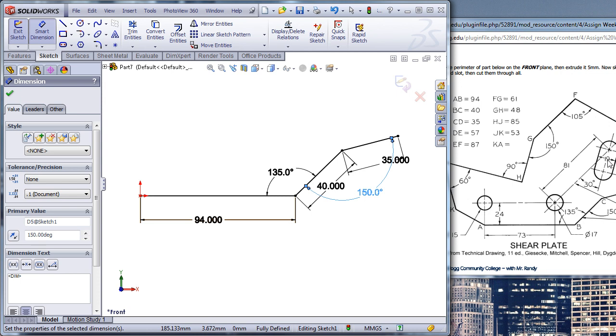You should be able to handle it from there. Again, don't do diameter dimension. This is 19 across the line, so draw the 2 circles. You could equal relate them. Draw the tangent lines, trim it up. You should be able to do a point-to-point dimension across those 2 lines, and then cut through all. Okay? There you have it. Good luck. That's kind of all the week 1 stuff really fast, and we'll see you in class.